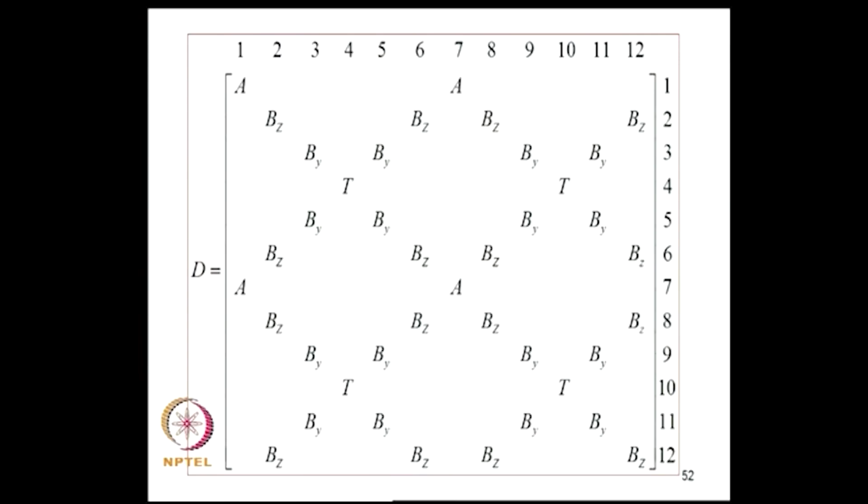So in principle we will be able to obtain the frequency response functions without resorting to modal truncation and without having to use piecewise polynomials for interpolating the field variables within an element. So this type of solution can serve as benchmark solutions to validate approximate methods, and these are quite flexible in terms of their ability to handle different damping models. So if you are doing a damping treatment for individual members etc., this formulation will give you a better hold on the problem. So we will not pursue this, it is somewhat a special topic, but it is useful to note that such solutions exist.